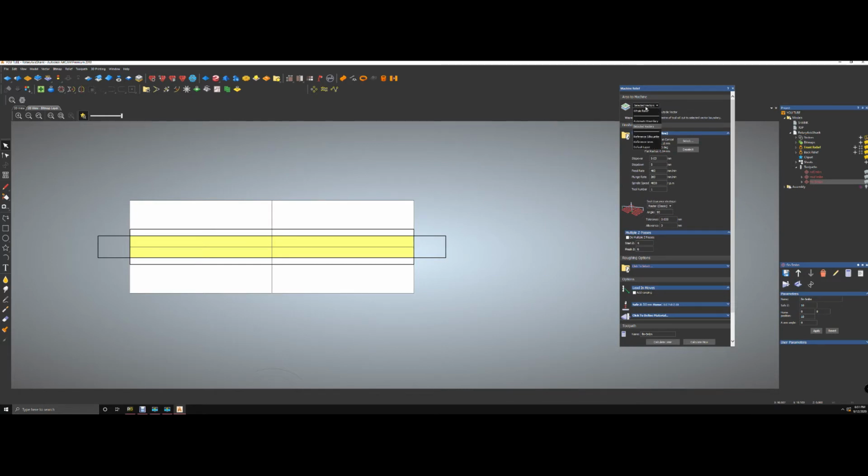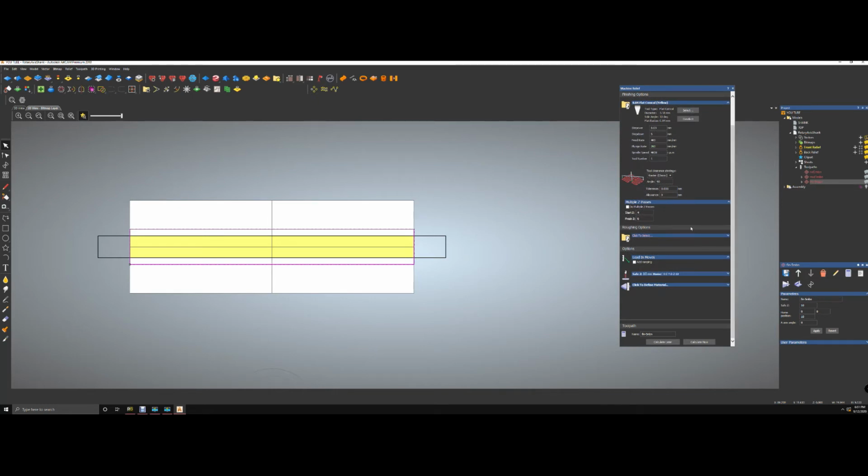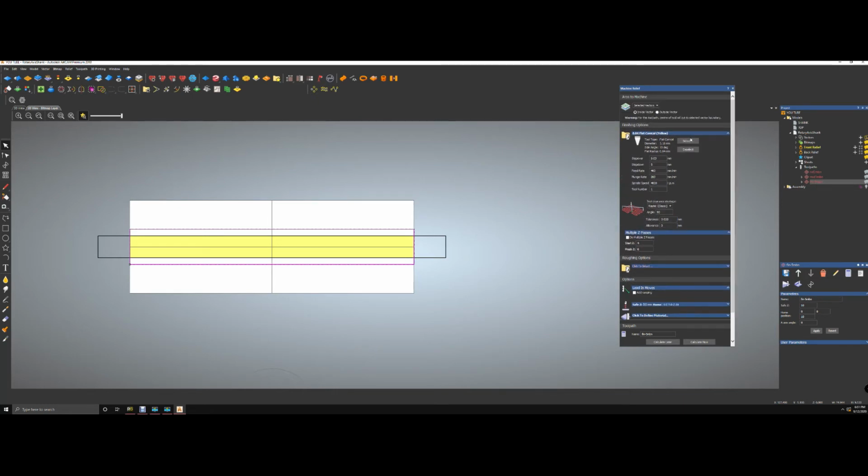If you see in here, it says you want the whole relief. I don't want to mill the whole relief. That's too much work. I just want to select the vector, which I'm going to select right now. You could change the step over. I usually keep it at 0.03 and a 90-degree angle. And the tolerance: the lower the tolerance, the cleaner the model. But really in wax, I clean it after by hand, which is much faster. A lower tolerance is going to take longer machine time, but it means it's going to be very smooth. So this number is a pretty good number. I'm happy with all these numbers. They're already pre-done for you.